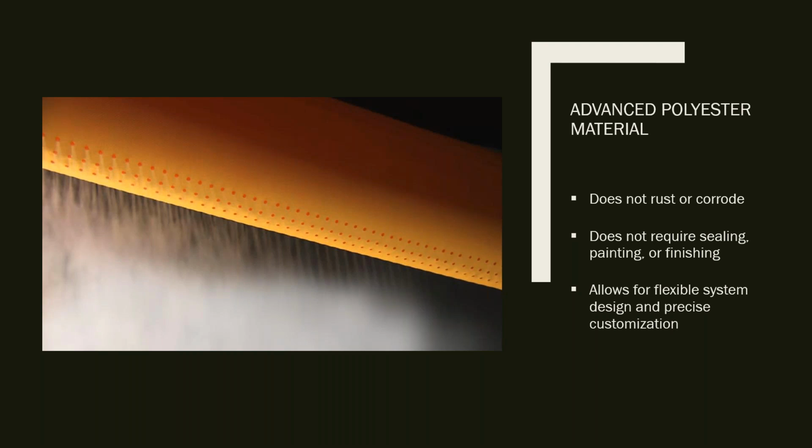They can also come in two different ways. Fabrics can be made permeable, which is like a breathable fabric that creates an air barrier that prevents any condensation from forming, or they can be made non-permeable. Non-permeable is used to transition air from one space to another. Let's say you have a gymnasium where you want to connect off a main trunk line of fabric duct and run it over into a room, maybe a storage closet. You would do that more so in a non-permeable fabric.